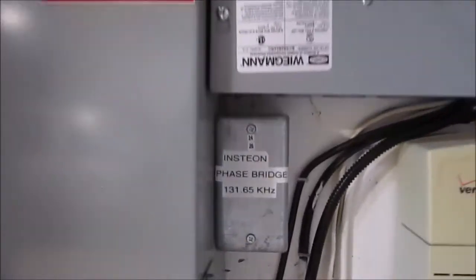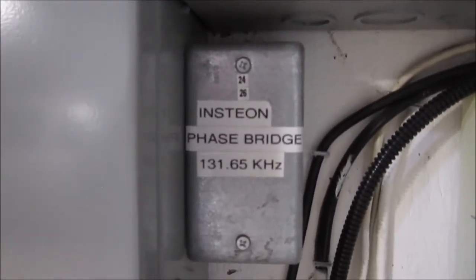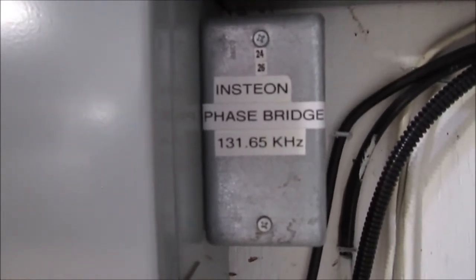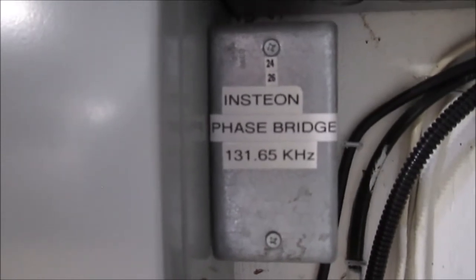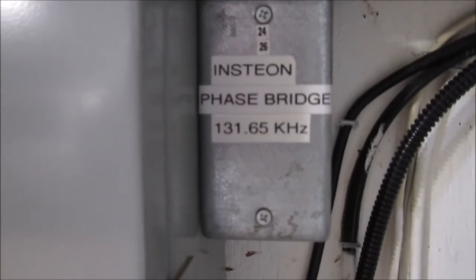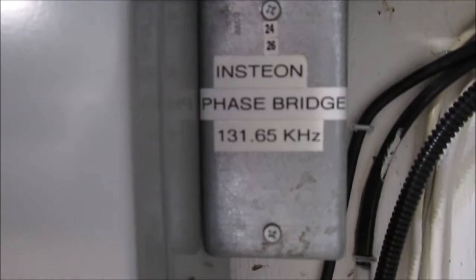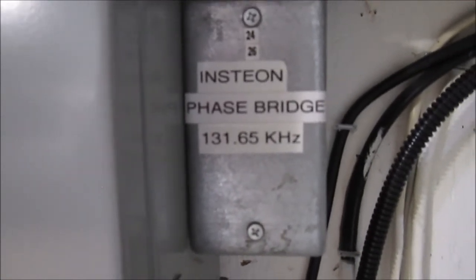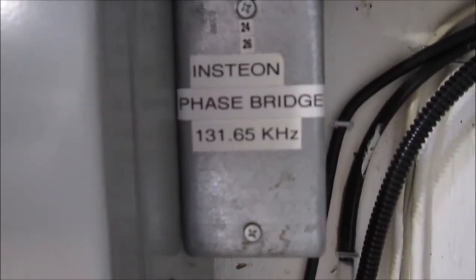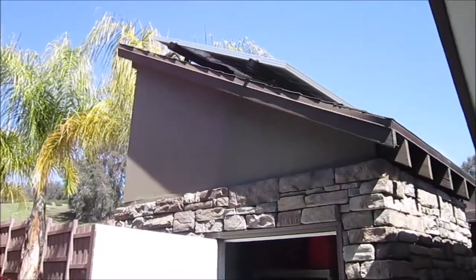And lastly, worth a quick mention, this is an Insteon phase bridge. If you remember, the signal is being injected for the home automation inside on circuit number 21, but that's a 120 volt circuit, so it's only the one leg. In order to get the signal throughout the whole house, you need to share the signal with the Insteon phase bridge. That way you connect both legs together and you can get full communication to every circuit in the house, outdoors, and so forth. Not sure if it's helpful.